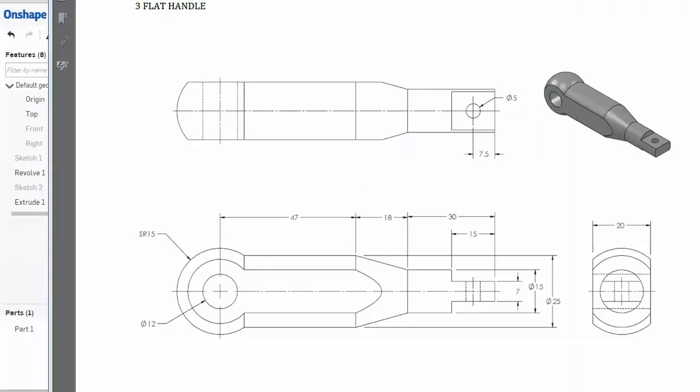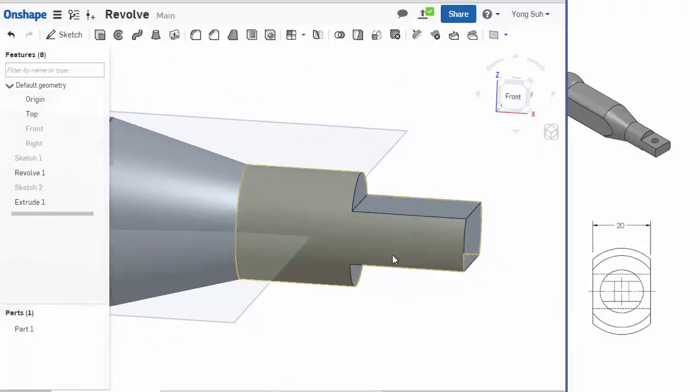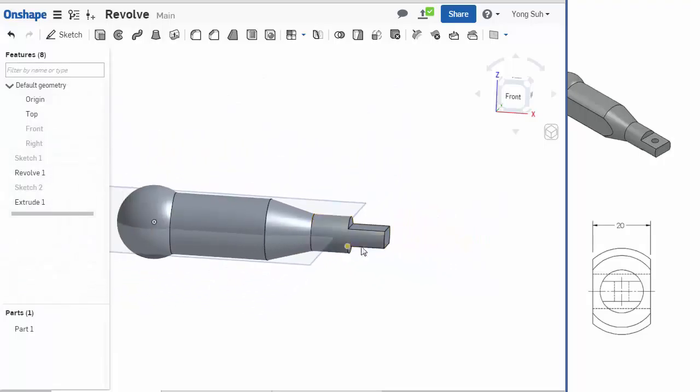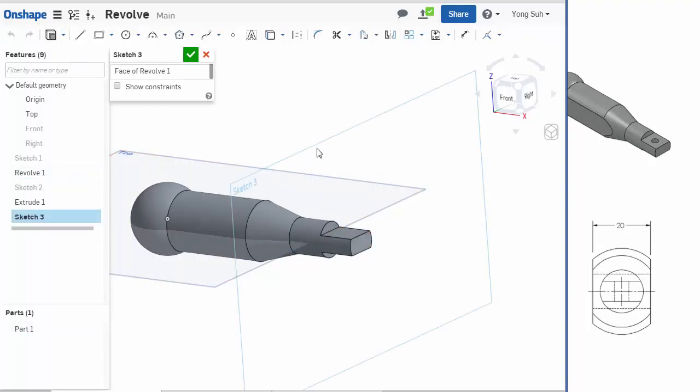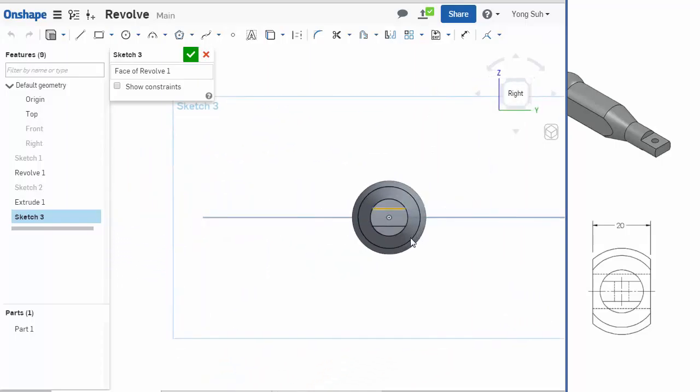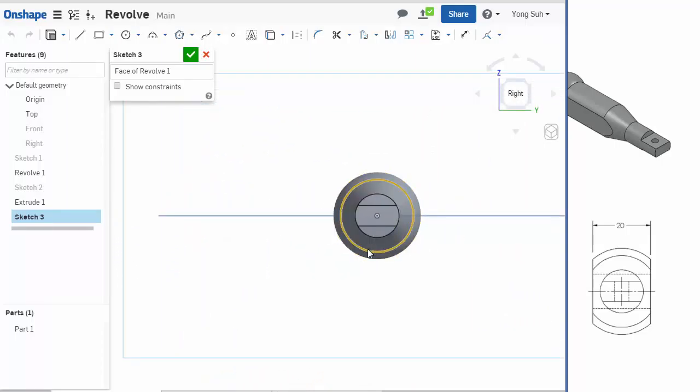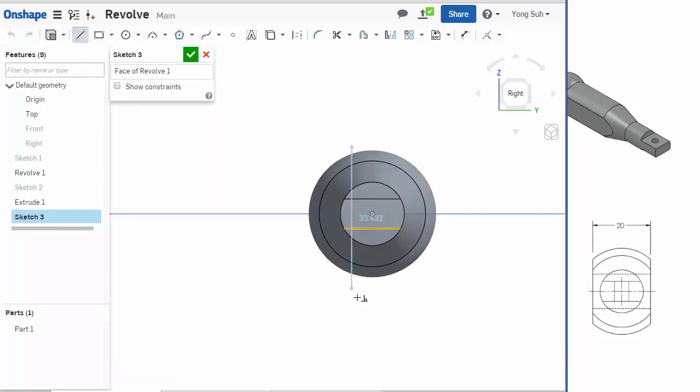So in order to do that, it's probably better to create a sketch at the end plane surface. So create a sketch there and look at normal to. And now I need to draw these two parallel lines. So I will draw a line here. I want the endpoint to be exactly on there, but it may not be easy to do that.